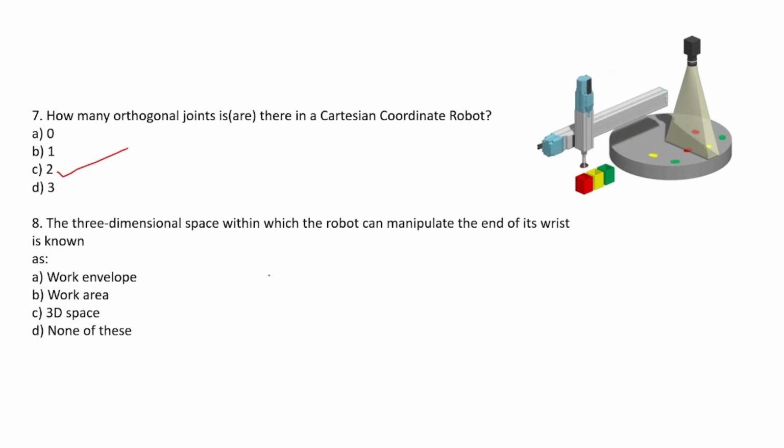It is similar to the jointed arm robot, except the vertical axes are used for the shoulders. And it is rigid in the vertical direction and compliant in the horizontal direction, for vertical insertion tasks. So that is SCARA. Then another one is the Cartesian coordinate robot, which we have seen right now in the figure itself.